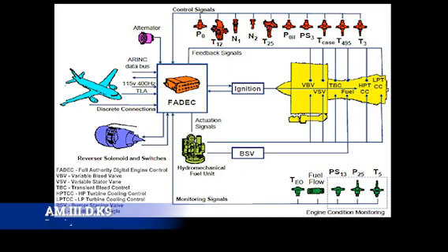Its components: you'll have an engine control unit, which is basically a core computer that monitors everything and makes decisions based on what the pilot's wanting to do. It has sensors, so your N1, N2, EGT, fuel flow, all these things that we're talking about all feed into that engine control, the ECU or the EEC, depending on manufacturer. And then it has small actuators all over the engine that help adjust components like fuel flow valves, variable stator vanes, bleed valves, all those types of things.